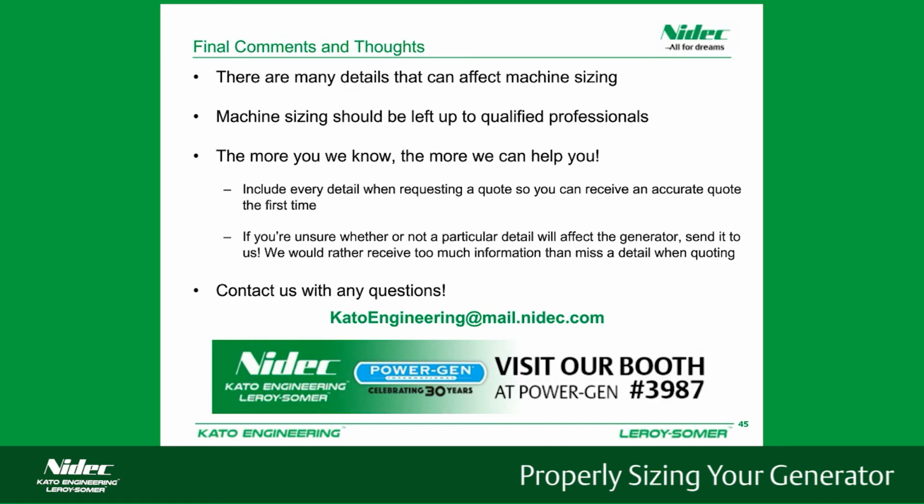Perfect, thank you. Okay, the next question we have is, what physical changes are made to the generator depending on the power factor selection? Particularly if we wanted a machine rated at a lower power factor, we may have to oversize the machine to give it a larger rotor to handle those higher rotor currents at that lower power factor.